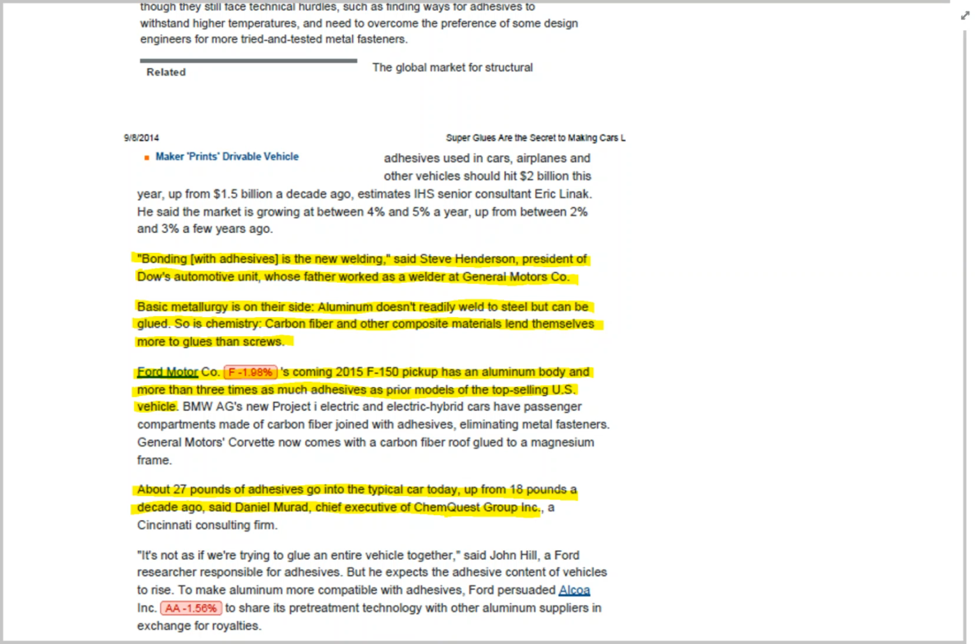And one of the things that caused was it facilitated, if you will, or it opened the possibility of getting galvanic corrosion, because now I have dissimilar metals, right? I've got aluminum and I got steel, and they will create a galvanic cell between them and cause accelerated corrosion over what you would normally get.